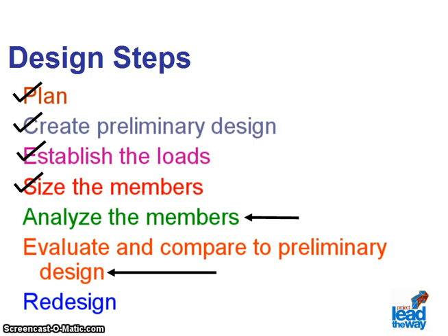Let's go back to our earlier discussion about the steps needed in structural design. Planning the structure to function for its intended purpose and optimizing the design in terms of cost, material type and weight, and the construction time are all part of the planning stage. This stage is done both by the architect and the structural engineer. The preliminary structural configuration was based on the layout required. The loads of the structure are determined through the use of construction standards and building codes for the site's location.